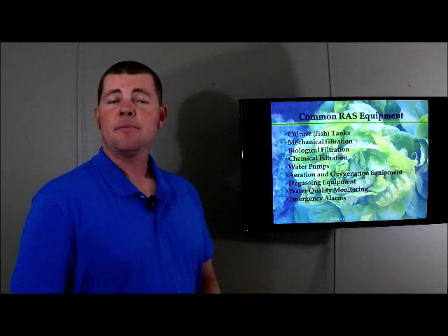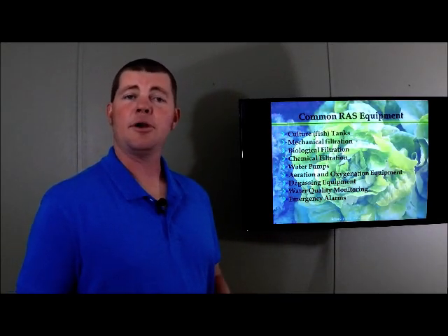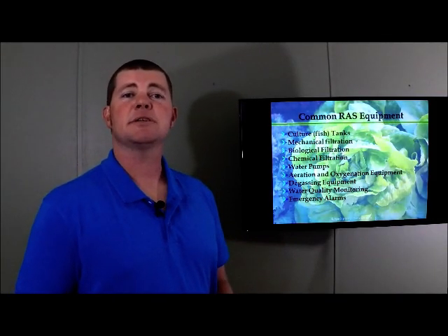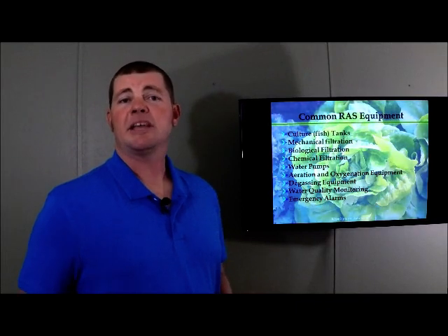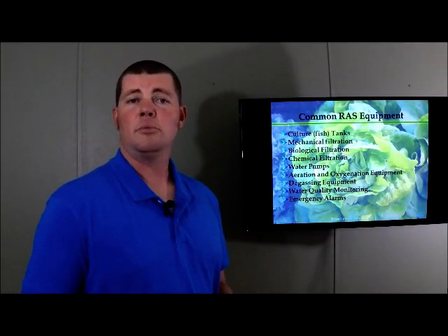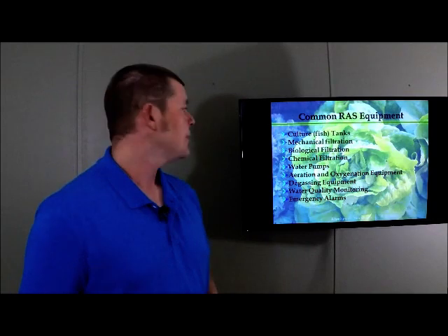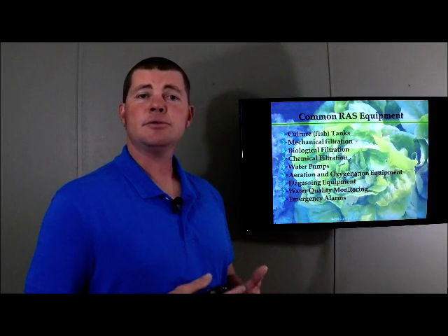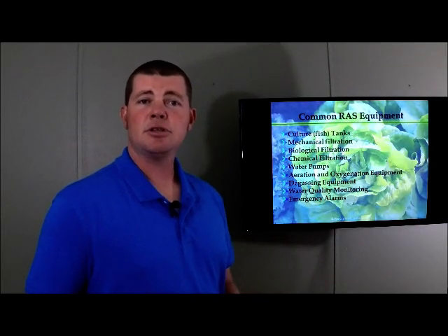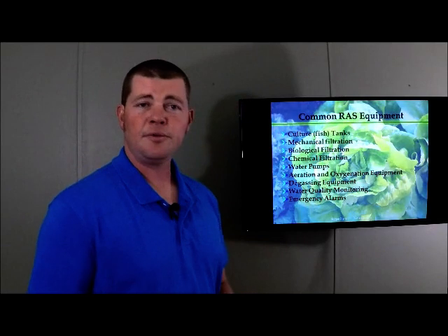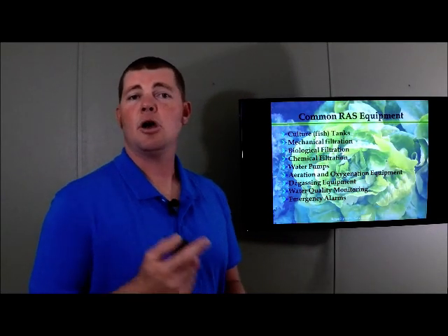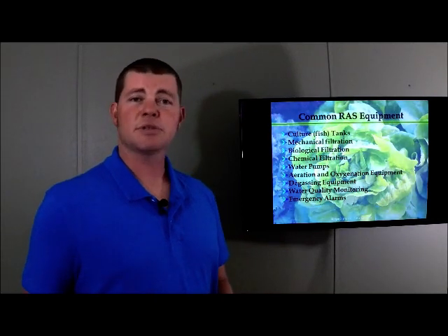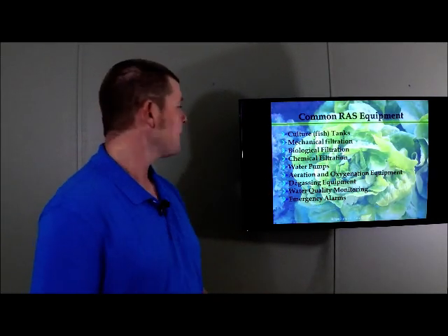Biological filtration is what we talked about earlier, our nitrifying bacteria. And biological filtration is going to process our dissolved nutrients, like ammonia, into harmless nitrate nitrogen. Chemical filtration would be used to disinfect and treat the water. So this would be UV sterilization, this would be ozone usage, and maybe even hydrogen peroxide, which we will talk a little bit about all this later.